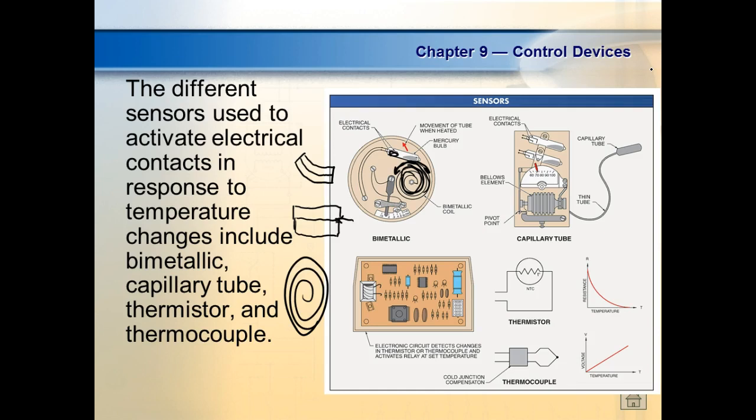Its resistance changes. So a thermistor, it varies its resistance with temperature. But the resistance it varies is not linear. Y'all understand that? So I'm not going to use a thermistor for an accurate measurement unless we combine it with some electronics that compensates for the curve.